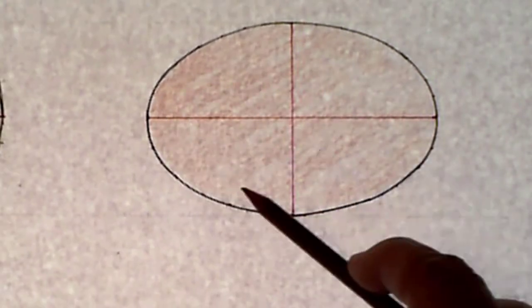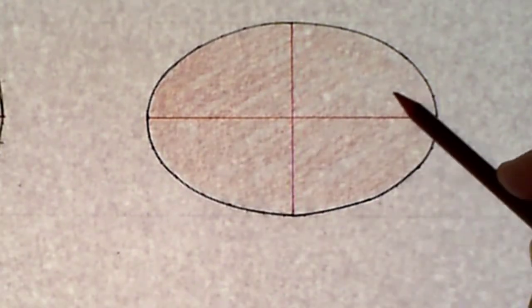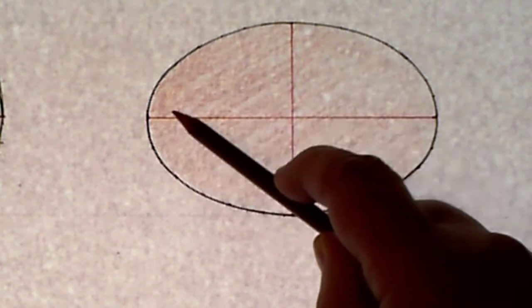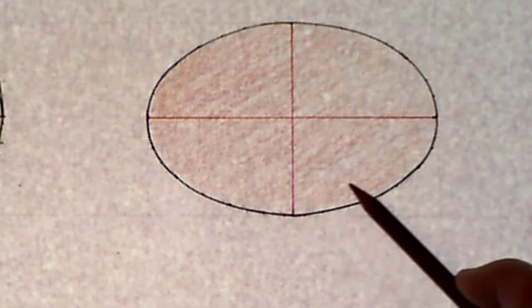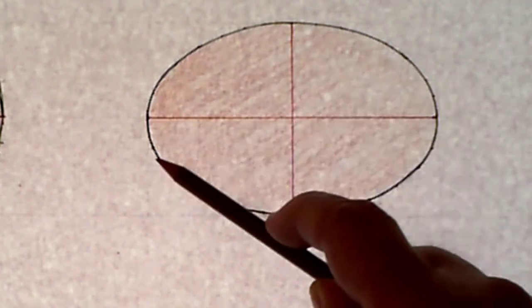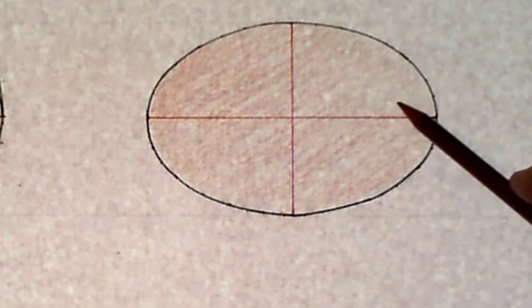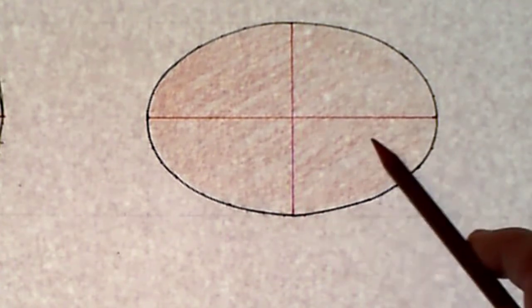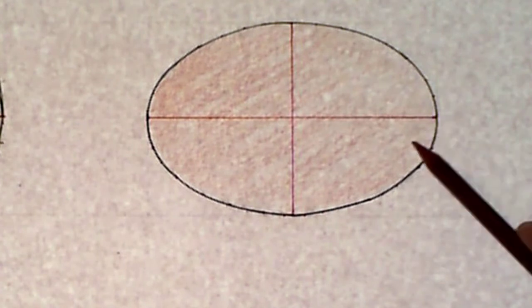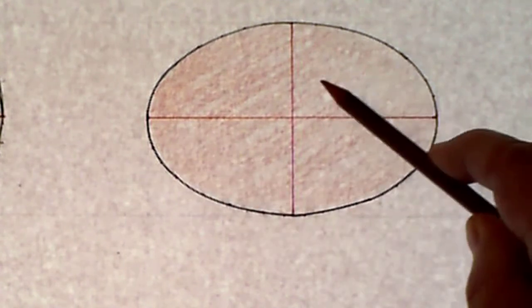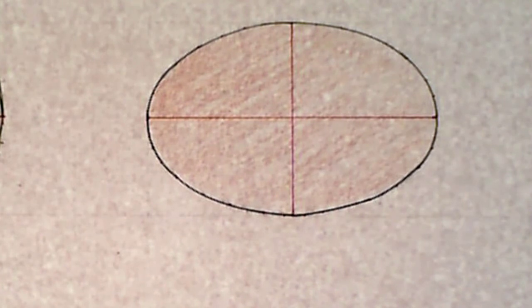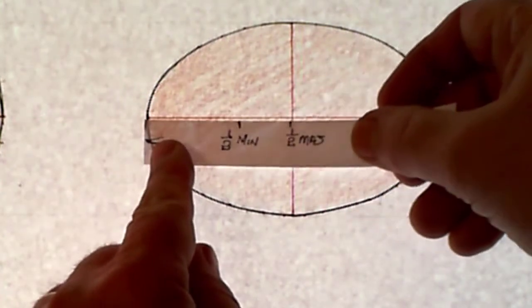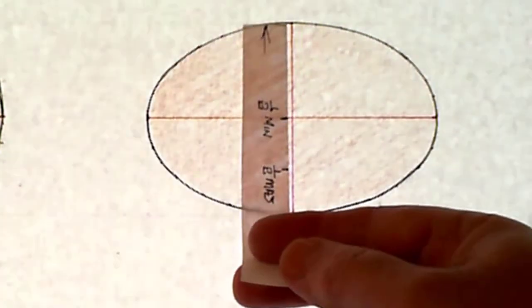Now, if I'm in a workshop environment and I want to use this particular method in order just to set out an ellipse, there's a way of doing it, and I will show you in a later video how to do it with string and either a few screws or nails in order to establish the particular points you need to establish in order to tie the string to. Now, how you establish those points, you need two focal points. So again, what we did here with regards to half the major by half the minor with regards to the piece of paper.